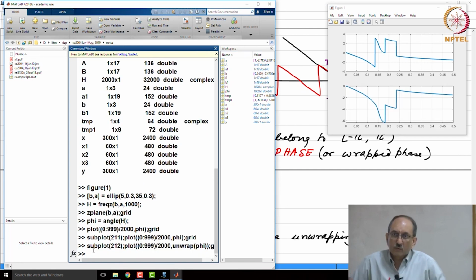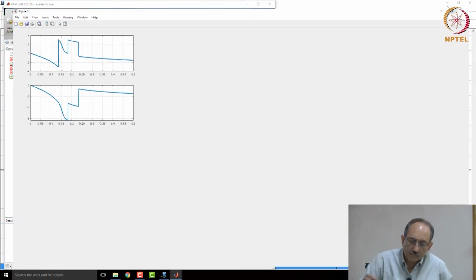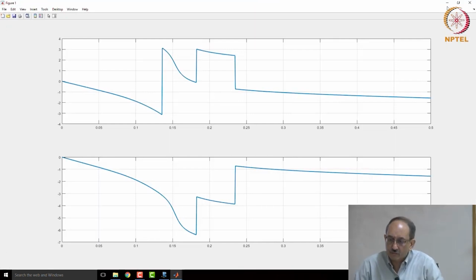Okay. So, this is the unwrapped phase. Now you see that this jump of 2 pi is gone, because you have unwrapped. So, now it keeps going. Now, you have hit the first 0. Unwrapping will not eliminate jumps of pi, it only eliminates jumps of 2 pi, and you have now jumped up, because this is a 0 on the unit circle and we are looking at positive frequencies.